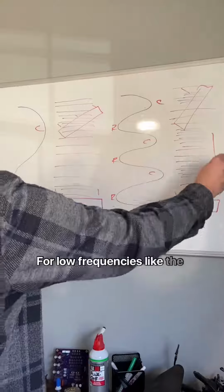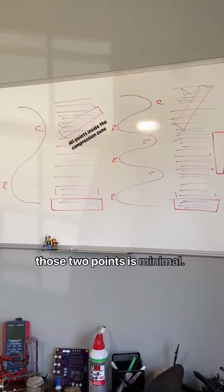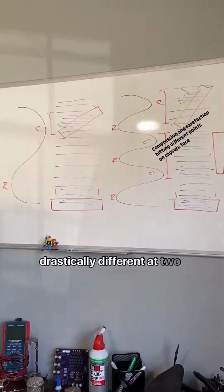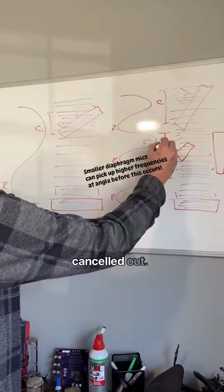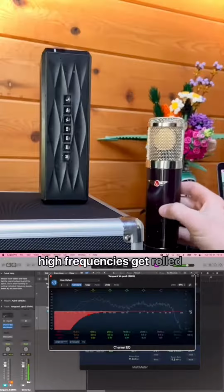For low frequencies like the one on the left, the wavelength is so wide that the pressure difference at those 2 points is minimal. At higher frequencies, we can see that the pressure is drastically different at 2 different points, and so the total sum across the entire diaphragm is getting canceled out. So that's why as we turn the microphone, we're seeing those high frequencies get rolled off.